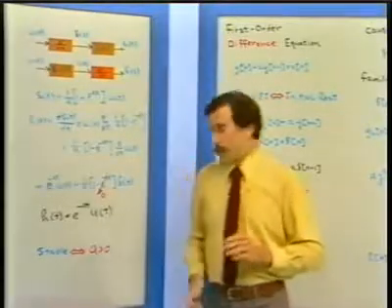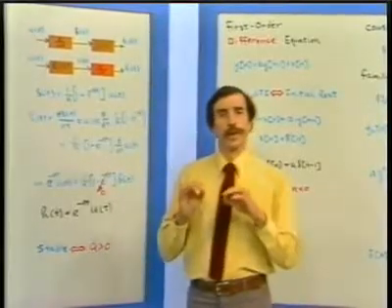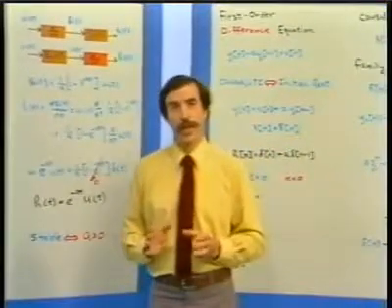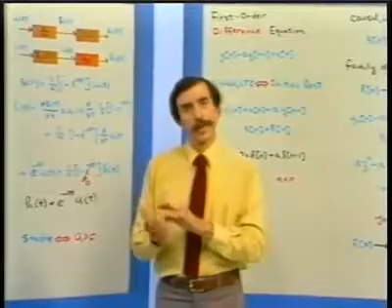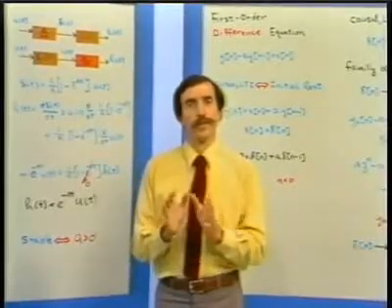Okay, so what we've seen then is the impulse response for a system described by a linear constant coefficient differential equation, where in addition we've imposed causality, linearity, and time invariance essentially through the initial conditions of initial rest.